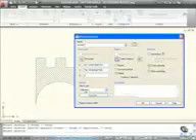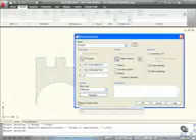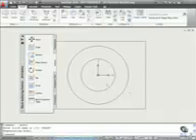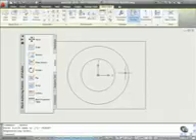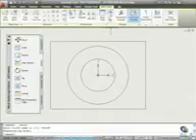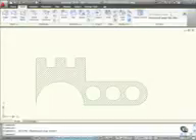Now in this particular drawing our block unit is in millimeters. We can add a hyperlink if we want to, perhaps to a specification or a bill of quantities. I'm also going to open it in the block editor, just to show you what the block editor does. When I OK that now, the block editor will kick in. Now the block editor allows you to make this into a dynamic block. We're not going to make any dynamic blocks, but you would utilize your block authoring palettes here to make it into a dynamic block. Notice as well, the block editor tab appears on the ribbon, and there's all your block editing tools here. I'm not going to make any changes, so I'm just going to click on close, like so.